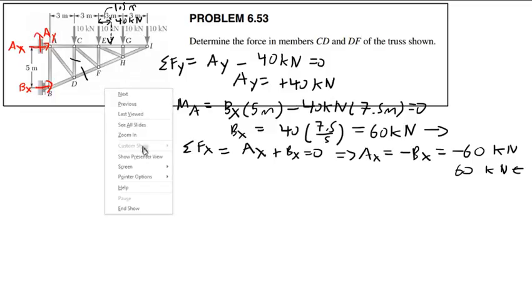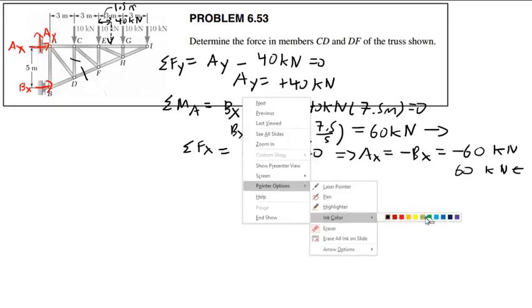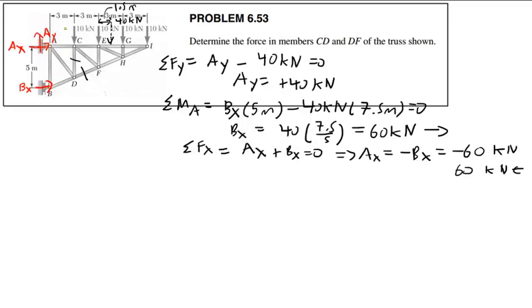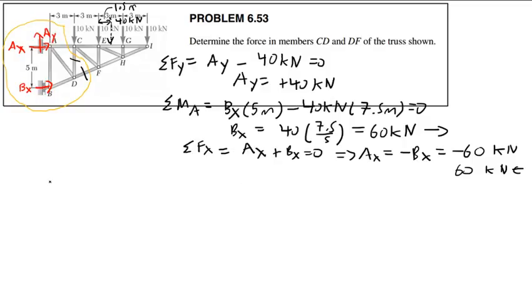So now I will simply, well, sort of simply, make a cut on this truss. And so I need to include this one, and I want to include only one other if possible. And it looks like I can do that just fine, like so. This piece here. So all this other stuff to the right is going to fall away, and I'm only going to be concerned with this piece here. And again, I'm going to draw it as a block, or in this case, a triangle.